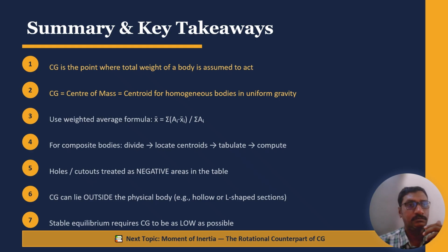Takeaway 2, the three-way equality for a homogeneous body, one with uniform density throughout, subjected to a uniform gravitational field, which is our standard assumption. The center of gravity, the center of mass, and the centroid are the same point. So in 99% of your engineering mechanics problems, you will use this equality. The distinction between these 3 concepts matters only in advanced problems involving non-uniform gravity or non-homogeneous materials.